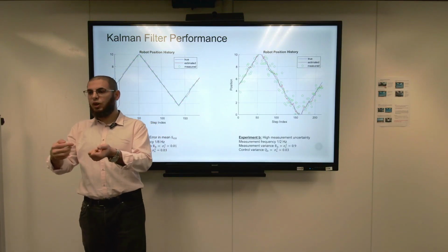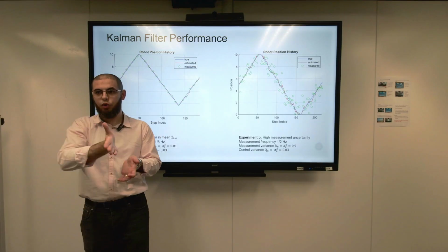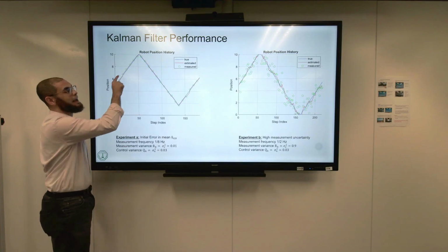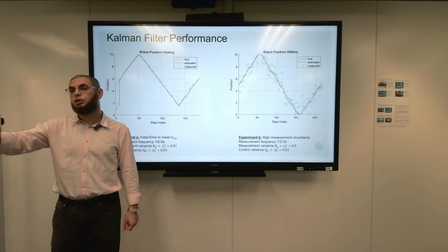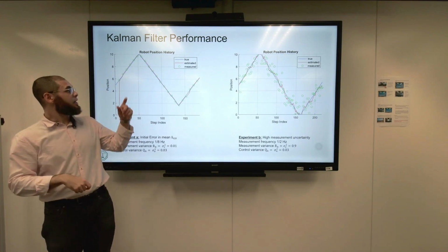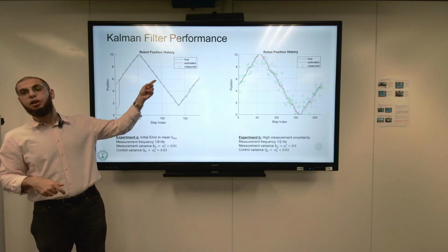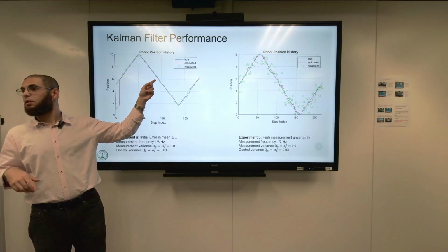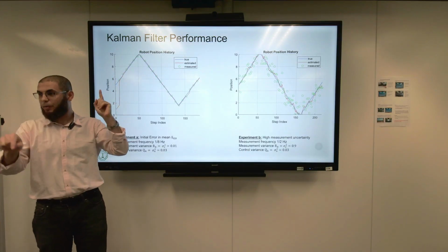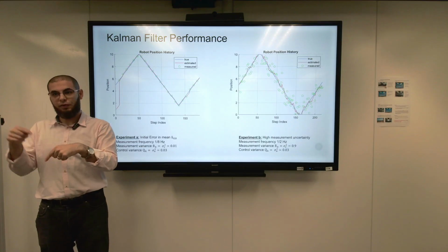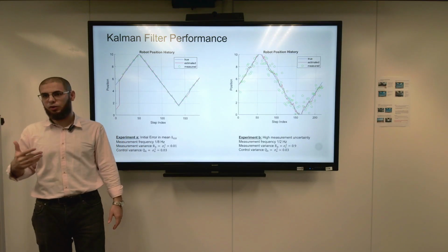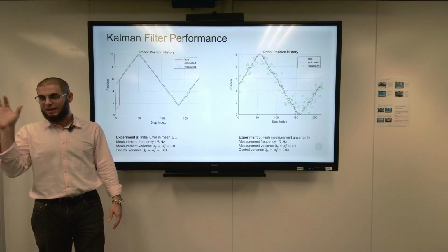But of course now when you're driving you find that you're following the path, going right and left. This is because the Kalman filter fills in the gap between both. It gives you a prediction at a much higher rate than what the measurement gives you. So in this scenario, we had a measurement every 8 seconds, while the state was updated every 1 second. Whenever you press the right and left buttons, every time step, you're always seeing how the robot moves. You have an estimate of where the robot is. Okay? So is that clear?